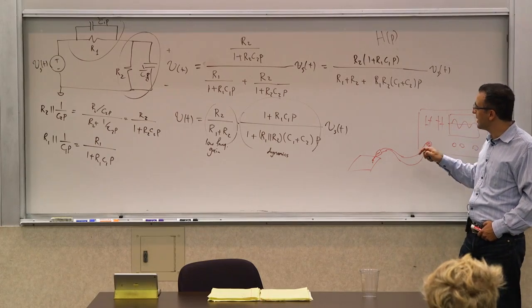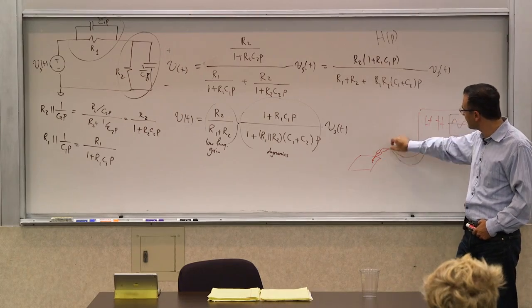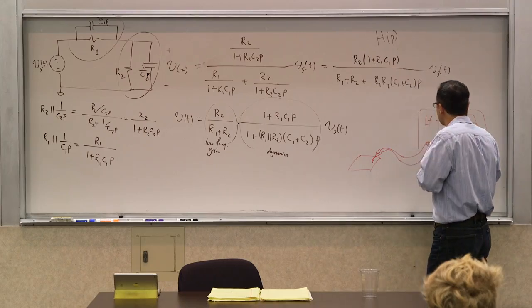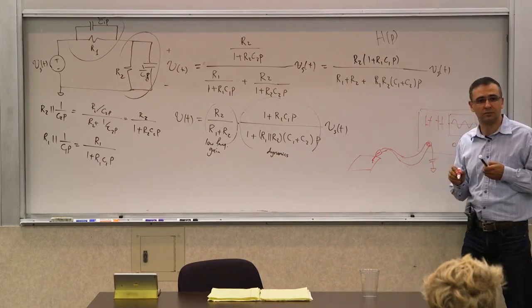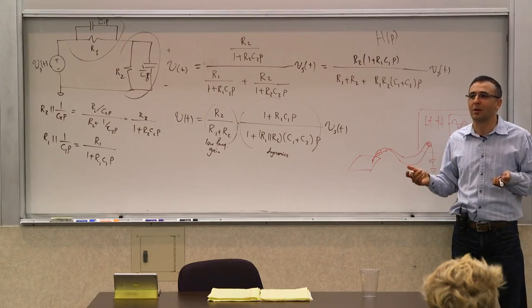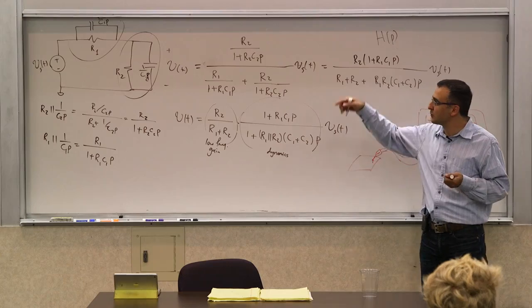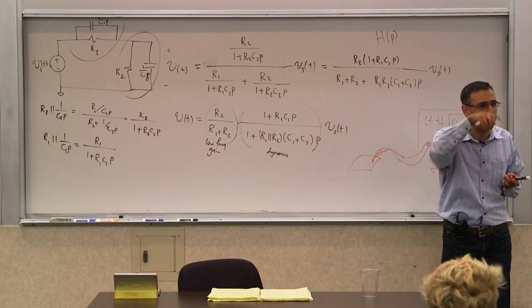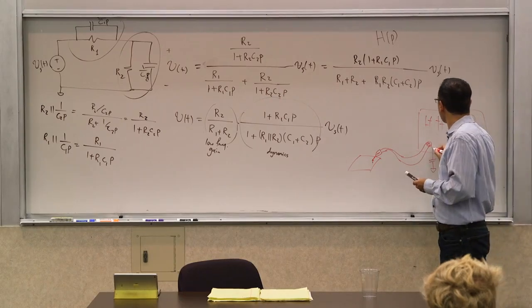So you want the voltage that the oscilloscope sees to be a good replica of this. But this probe and this oscilloscope and everything, the oscilloscope input has some capacitance, right? So it has some input capacitance. You can't make something that has no capacitance. Now, if you just hook up this capacitance there, it will start degrading the signal, because if you're looking at something high frequency, it will just bypass it and filter it and reduce the signal. So it also has a resistor.